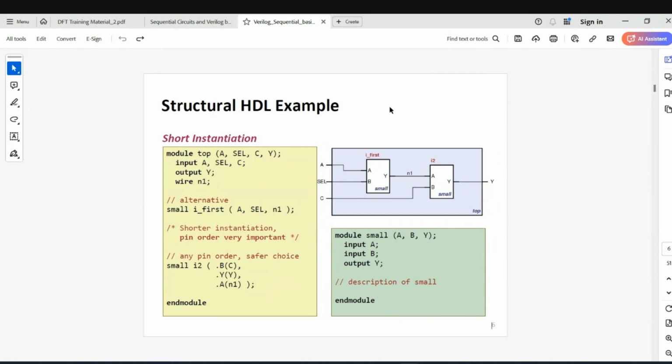For that, you should understand the Verilog construct, how RTL constructs look and how netlist constructs look. Most of the time, RTLs will not be traced, only the netlist and the schematic. Tracing in the RTL is very difficult in real time, because there will be multiple calling functionalities, and sometimes RTL is written in SystemVerilog format. So we don't worry about RTL. We worry more about the netlist, which will look similar to this.